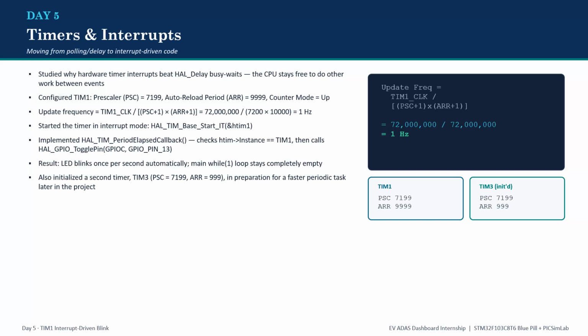I started the timer in interrupt mode using HAL_TIM_Base_Start_IT and implemented the HAL_TIM_PeriodElapsedCallback function. Inside it, I checked that the interrupt actually came from timer 1 and then toggled PC13. The result is the same blinking LED as day 2, but now the main while loop is completely empty. The blinking happens automatically through interrupts in the background, freeing up the CPU.